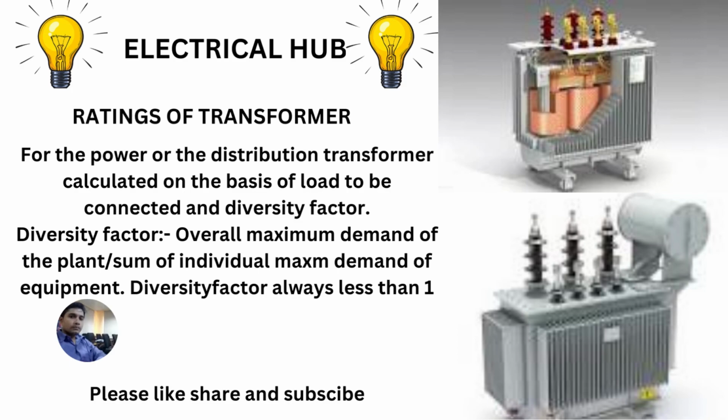Now, the rating of the transformer for the power or the distribution transformer, the rating of the transformer is calculated on the basis of the connected load and diversity factor. Connected load means from the source where you are taking the load, or what amount of load you are going to take from a source. And the diversity factor is the overall maximum demand of the plant by the sum of the individual maximum demand of equipment. Diversity factor is always less than 1.